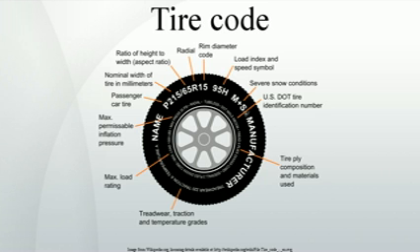While all ETRTO tires of the same load index will have the same maximum load, P-metric tires with the same load index may have different load capacities depending on the tire size. The TRA inflation tables must always be consulted when comparing the load capacity of P-metric tires. The load index alone is not sufficient.